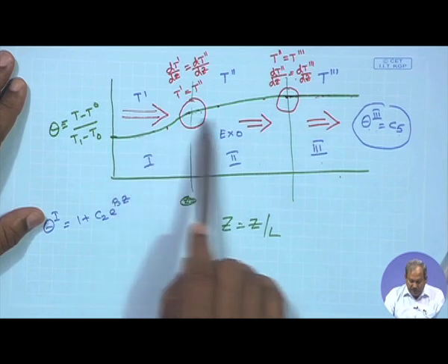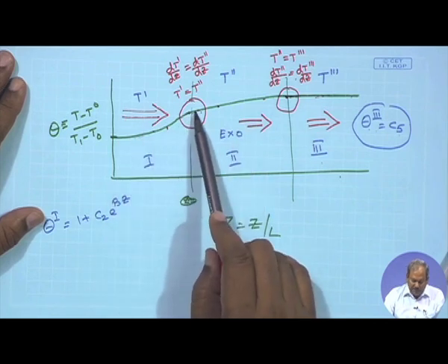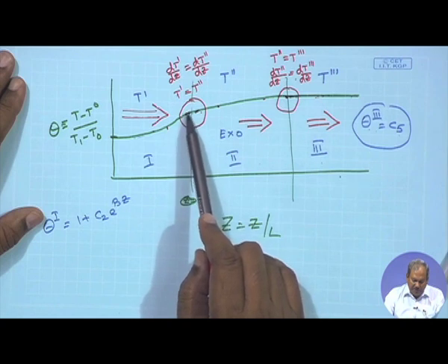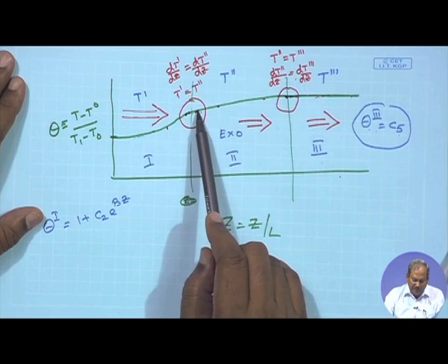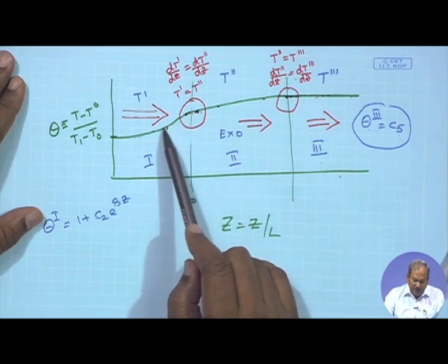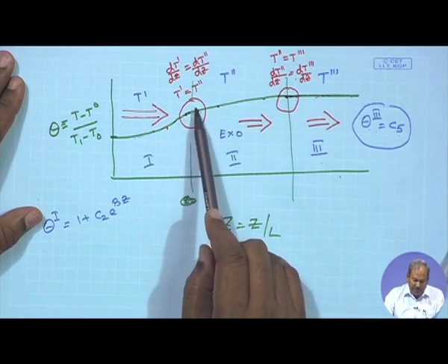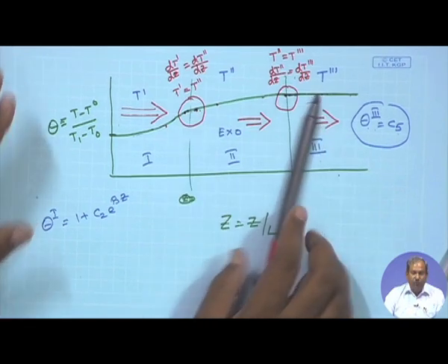If you understand that, then this is very clear. The convection is from left to right, but due to the difference in temperature, since an exothermic reaction is taking place over here, the temperature at this point must be greater than the temperature at this point, and whenever there is a temperature difference, there would be a conductive flow of heat which you cannot stop. So, the entering reactants are going to be preheated due to the exothermic nature of the reaction which starts at zone 2. So, the entry of zone 2 will result in an increase in temperature of the mixture.